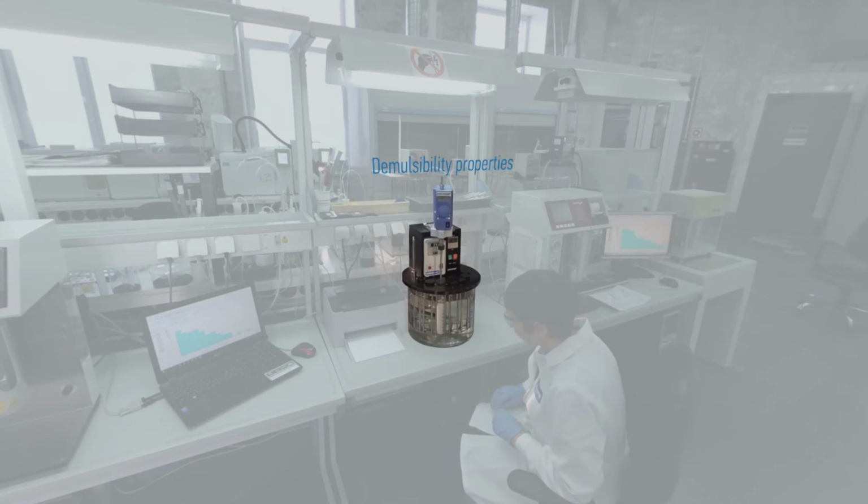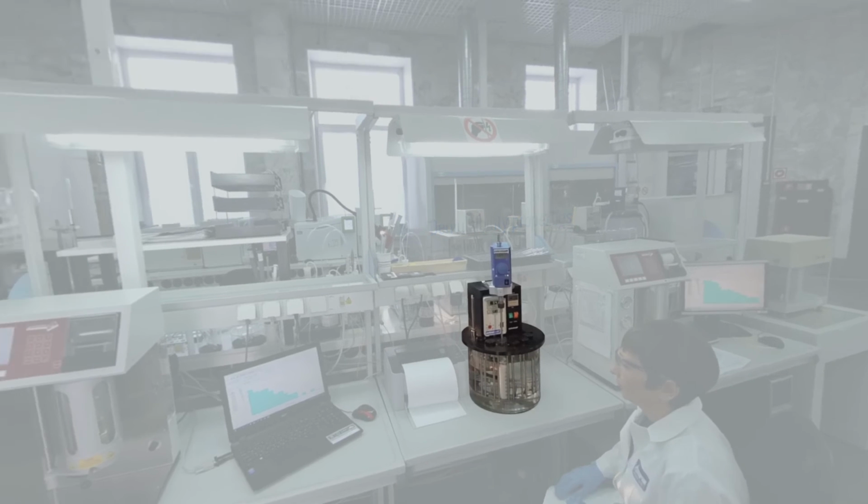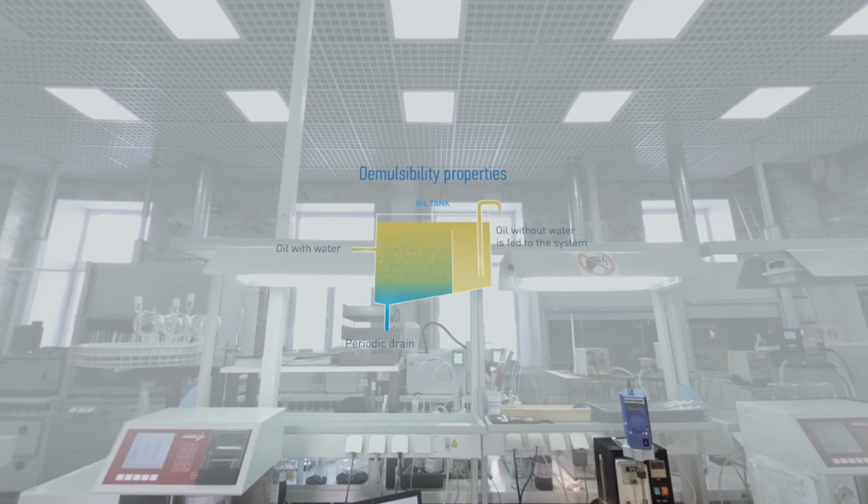Demulsibility properties of the product are its ability to separate water which may penetrate into the lubricating system during operation. The mixture in the oil tank has enough time to settle, and the oil without water returns to the lubricating or hydraulic system. This indicator is especially important for oils in contact with water or steam.